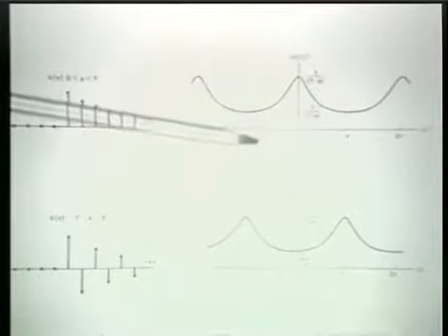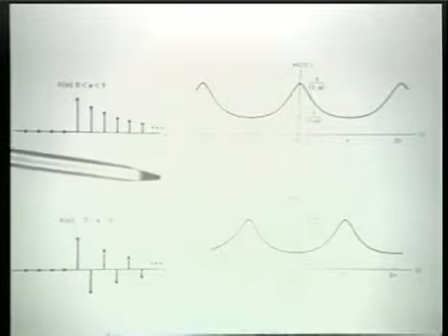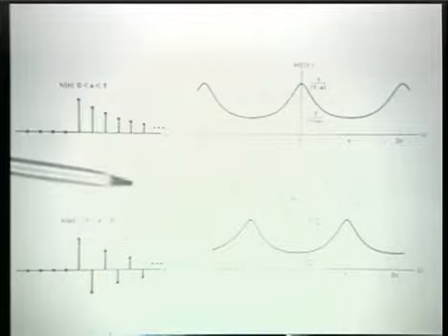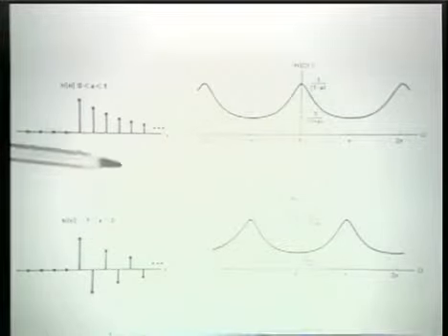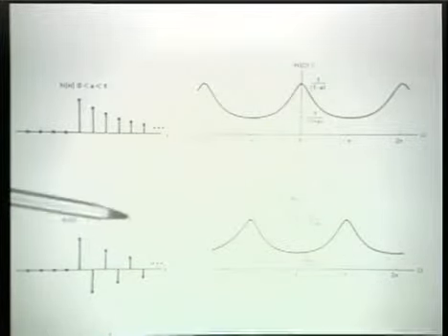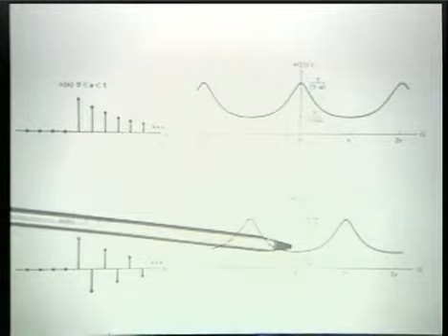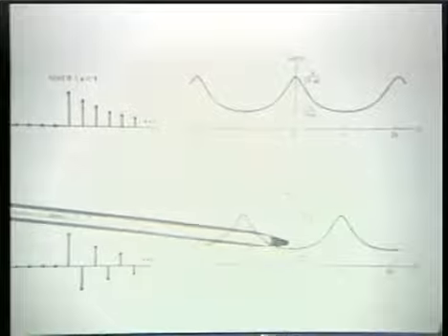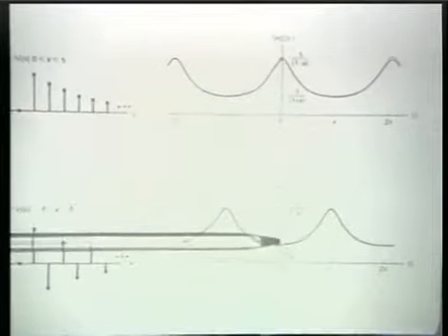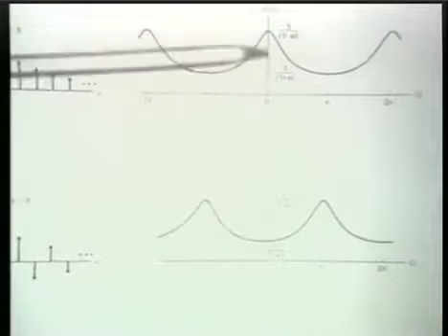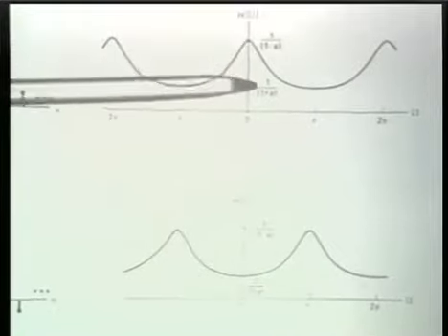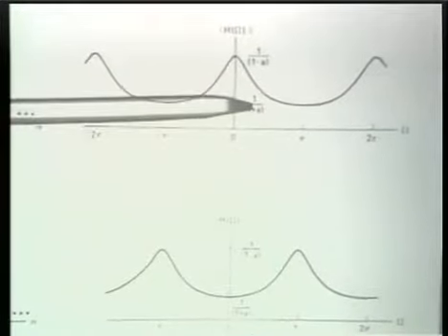For a negative, the sequence is identical to a positive, but with alternating signs. And the Fourier transform of that, you can now see and verify also algebraically if you'd like, is identical to this spectrum, simply shifted by pi.